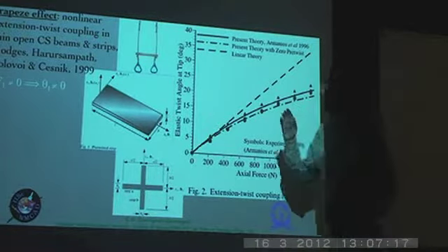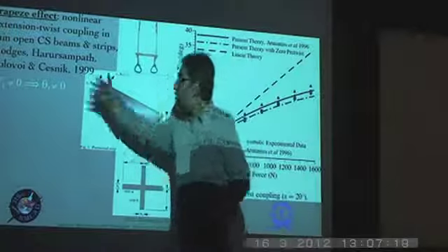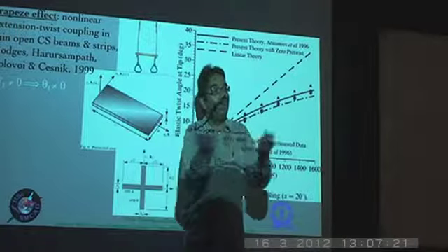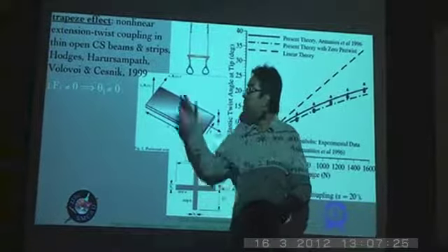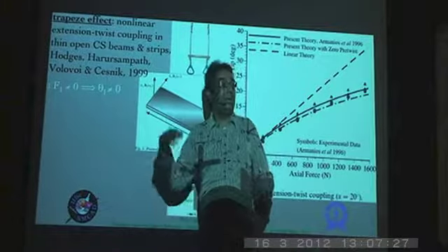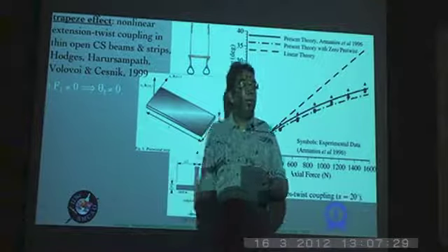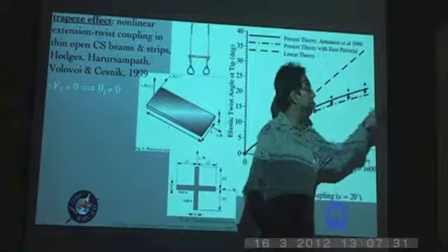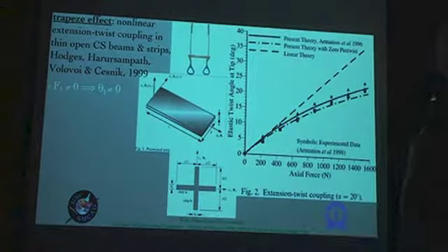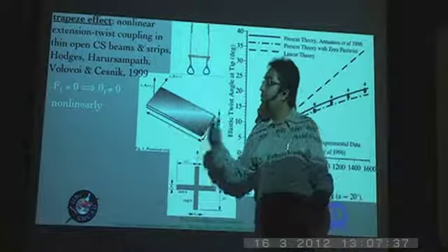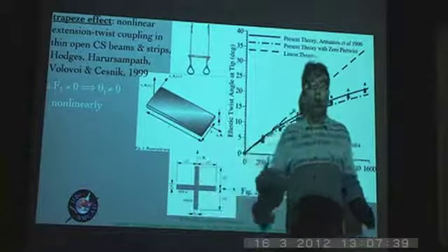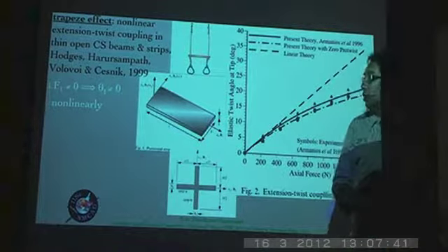Okay. So basically what it says is that if there is a non-zero value of your tensile load, or rather axial load, it could be tensile or compressive, basically theta 1 is not going to be 0 anymore. It is going to be affected by that because of the non-zero value of your S12. That is the first thing. But the more important thing is that this relationship between them is nonlinear. In other words, S12 is not a constant.